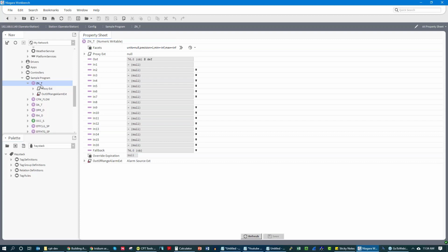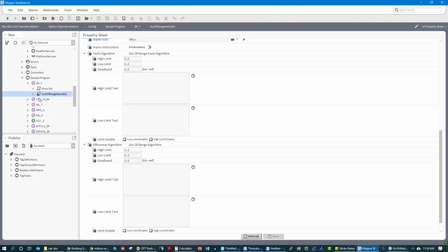Sequencing, yeah, it's great to have sequence standards, but oftentimes the folks who operate the building are not involved in the construction process. So their ability to validate the sequences are actually properly implemented is hit or miss. So I would focus on those three things which directly impact the operator. All right, so going back to alarm extensions, you set these up. When the point goes out of the alarm range, it generates an alarm that shows up on the user interface.